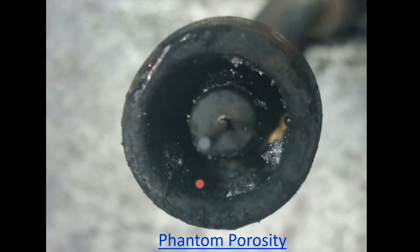But it does lend to the people who do the actual welding. You got to make sure you keep your gun clean. You don't have a reaming station. It would be kind of cool, but you don't have a reaming station. You've got to keep your gun cleaned up manually.